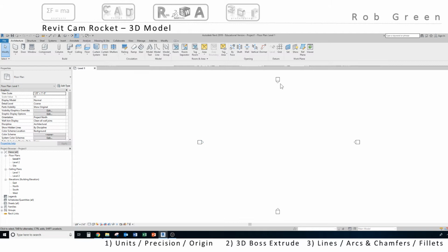I see 4 baseball-shaped home bases. Those are cameras that define east, north, south, and west elevations. I'm not going to need any of those for this project. But I also see over here that I have a level 1 that is bolded and a level 2 that is not bolded. I'm going to click on the south elevation simply to demonstrate what those level 1 and level 2 words mean.